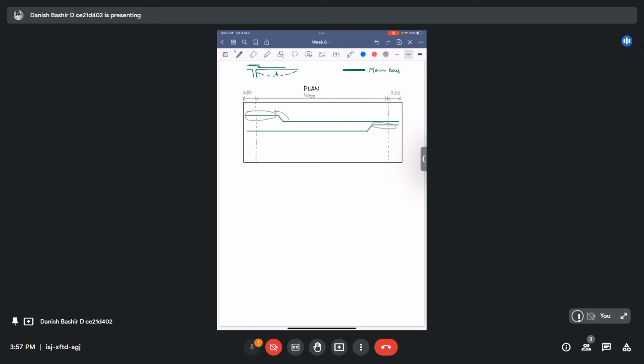Okay, so we can write this as, we have to write it here: this was our 10 mm diameter bars at the rate of 125 mm center to center. We also provided these distribution reinforcement bars, orthogonal to the main reinforcement, like this.